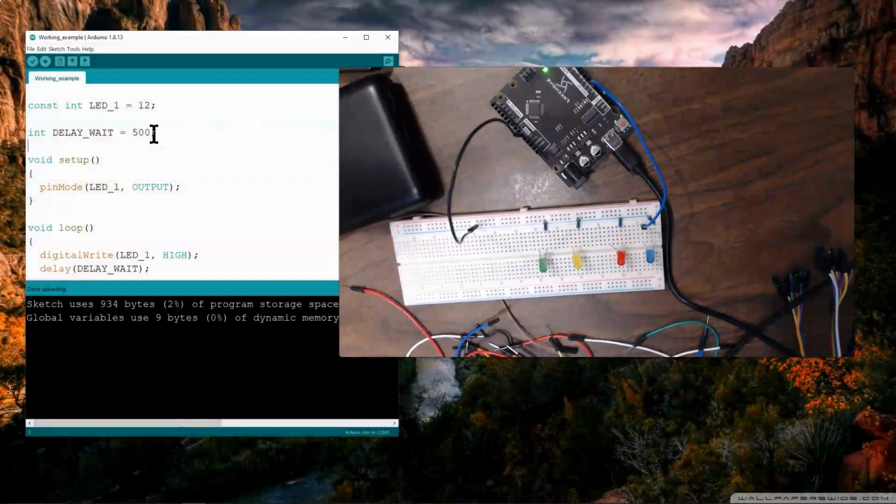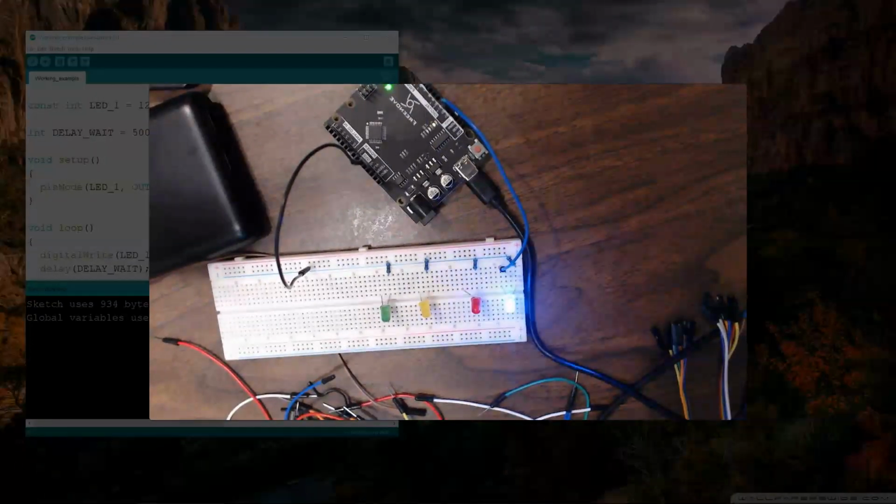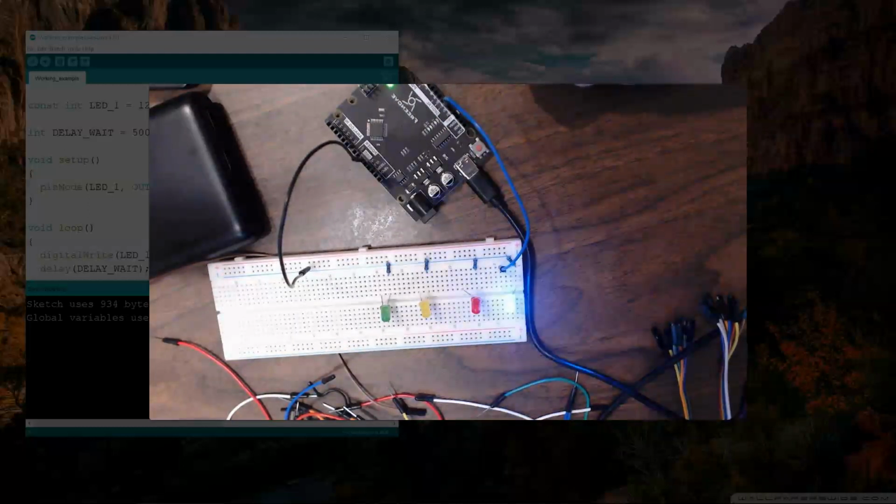Right now it's just going to always continuously keep running that program. If I want to restart the program without unplugging it, there's this little red button down here. This is the reset button, and if you press that, basically the Arduino turns off, restarts itself, reloads the program and starts from the very beginning. So it's like a little quick fix.